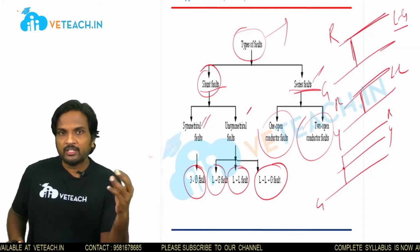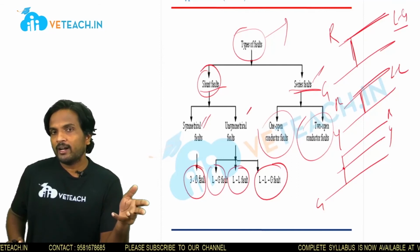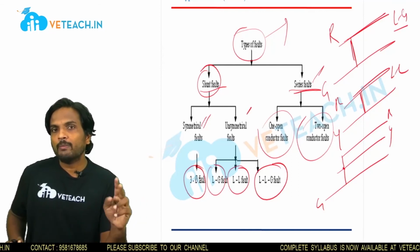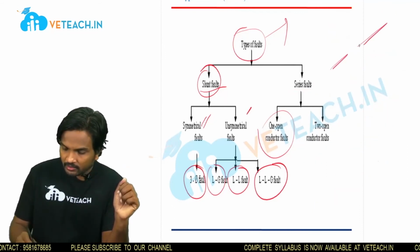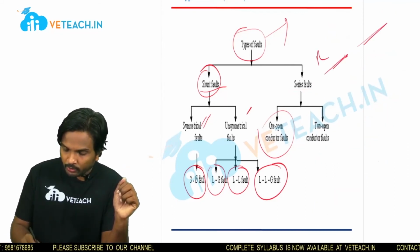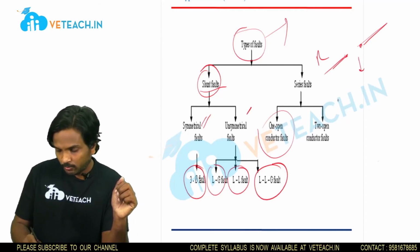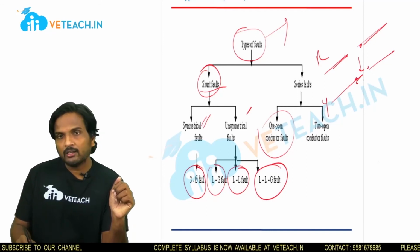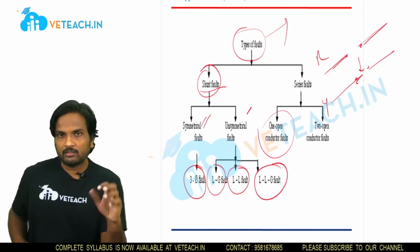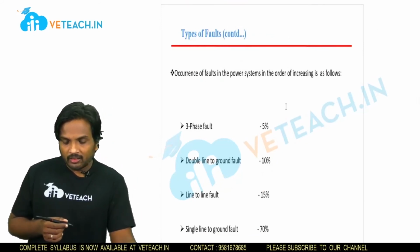Coming to series faults, they are classified into two types: one open conductor fault and two open conductor faults. See here, suppose you have a conductor like this, and one conductor gets open circuited, then it is called a one open conductor fault. Suppose the Y line also gets open circuited, then it is called a two open conductor fault.